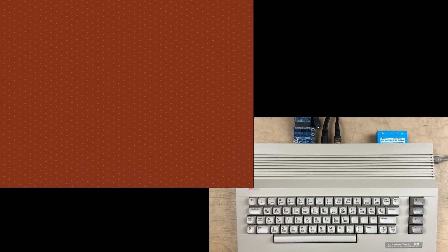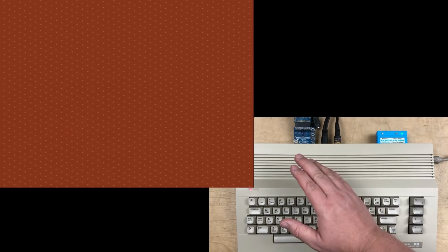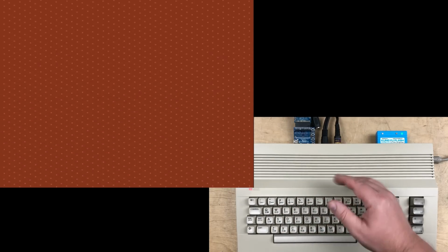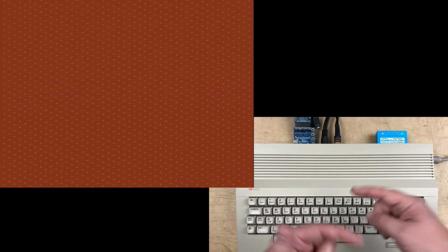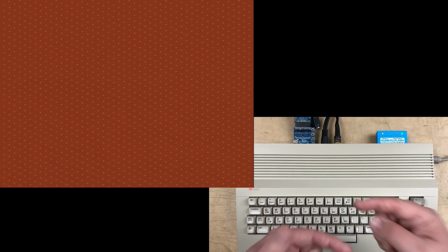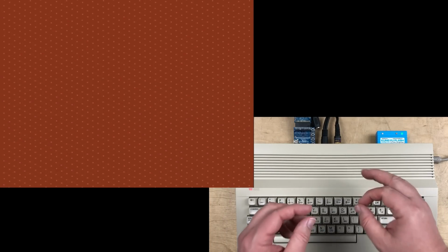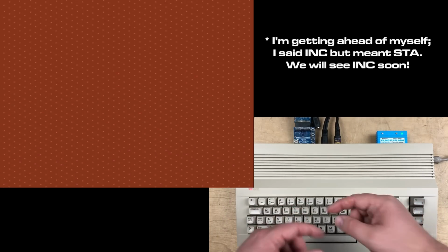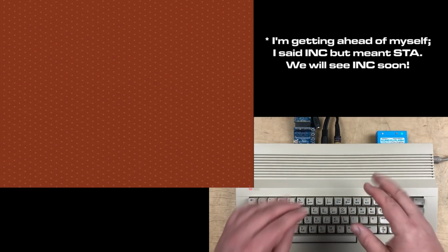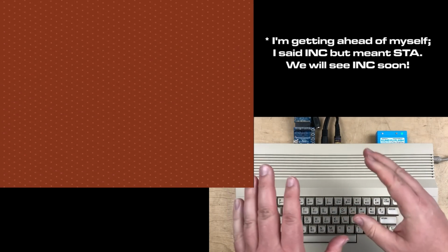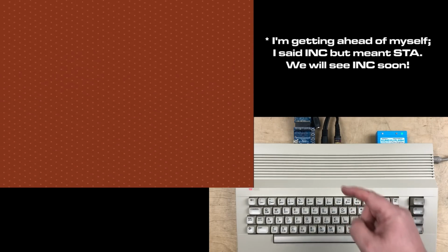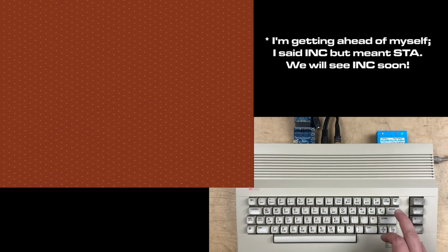Okay, I probably also didn't explain very well. The reason the dots are covering the screen is that the screen is being drawn top left to bottom right, and as the CPU is ticking along, incrementing, it's just busy doing that increment and jump, the screen's being drawn. So it's whatever part of the screen's being drawn at that moment that the ink happens, that these little dots will appear. And it's just the math of it, the timing of it, that makes it look like this animation. I think this will become a little bit more clear later.